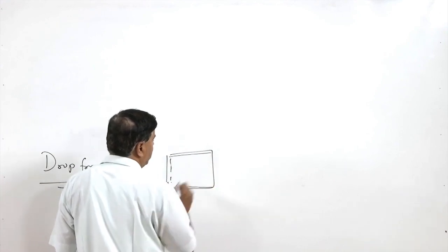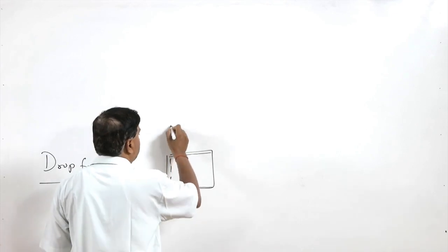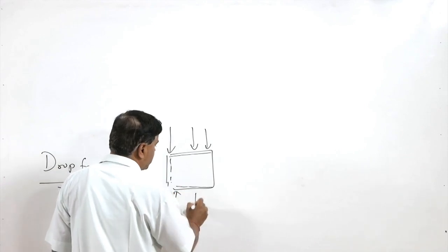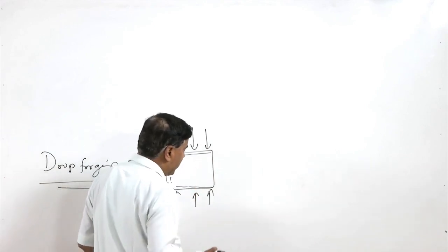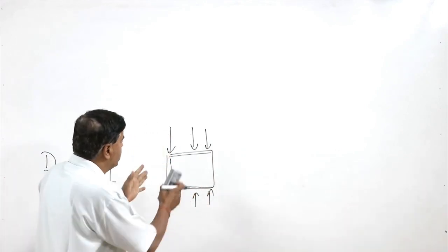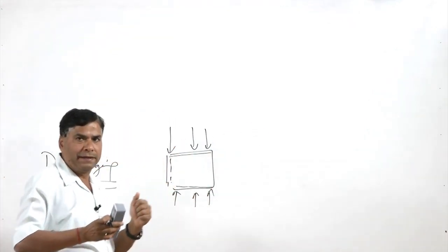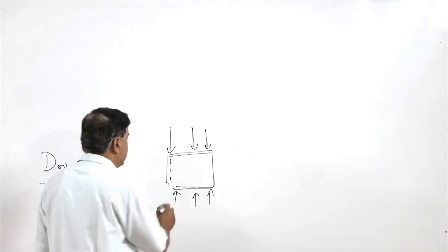So, this is the upper surface which will be experiencing the impact of the upper die, and the lower surface will also be experiencing the impact of the upper die, and because of these impact forces, the metal will be flowing sidewise to occupy the cavity in the die.